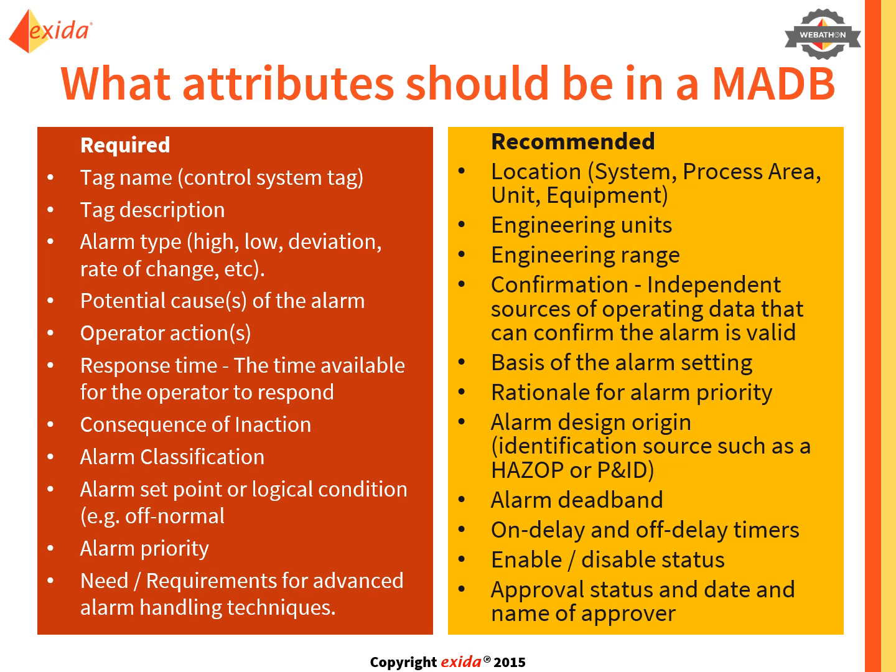A tag can have several alarms associated with it, as in tag name TI1001. That could have a high alarm which will be called TI1001_high, and so on.